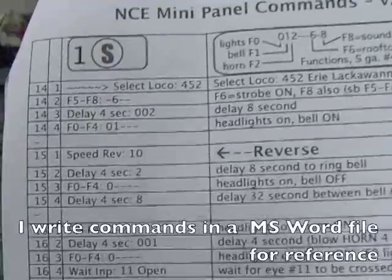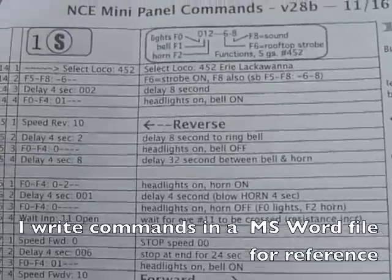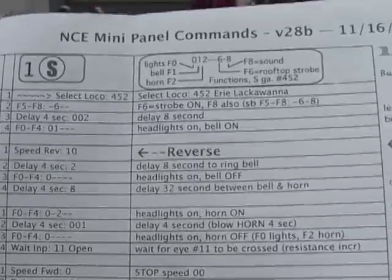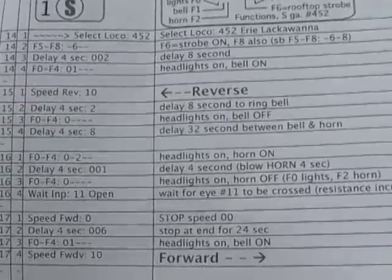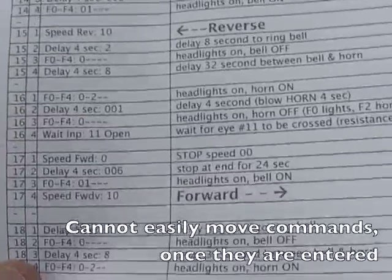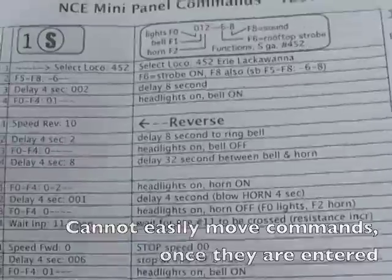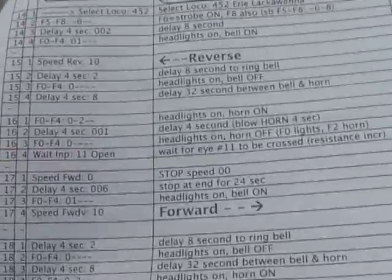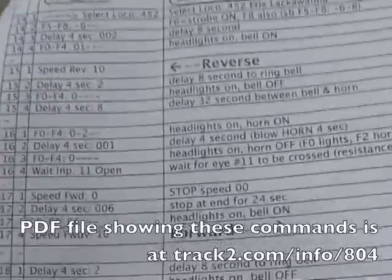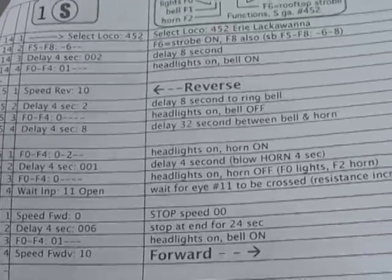I mentioned earlier I write all these commands down in a Microsoft Word file before I actually start programming anything into the mini panel. A reason for doing that is you can't really move commands up or down. To explain that better, if you've ever programmed in BASIC or Fortran or COBOL or Pascal or whatever the newer languages are, if you want to insert a line of code in a computer, you just insert it. Well, you can't do this here.